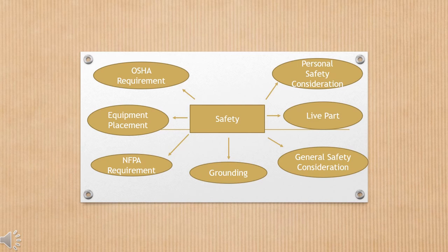The last one is grounding. In the grounding, all instruments are capable of developing internal faults. The instrument power supply should be properly grounded through a 3-wire cord.